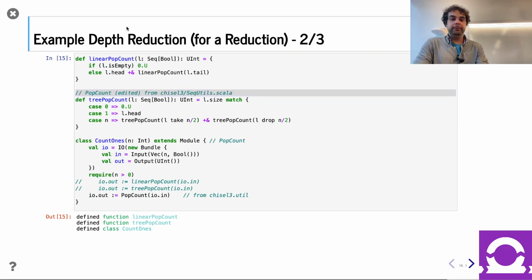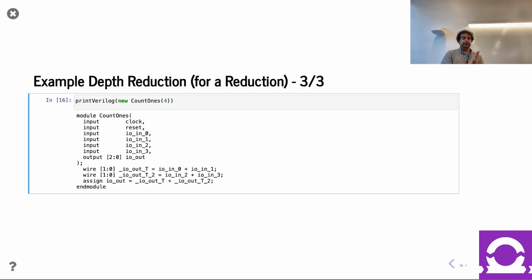So that's today's lecture on delay. Hopefully you got a flavor for this. Remember, delay in the real design comes from gates and wires. The tools do a lot, both to analyze and fix this. However, at times they get hung up, and that's where we can come in and help. The most common thing we're going to end up doing is inserting registers, helping with pipelining. And that's an architectural change. It needs to be done by humans for now. Hopefully, we'll have tools to automate that someday in the future. And then other times, like I just demonstrated, there's a logic depth issue. Very commonly this happens in priority encoders or things like that. And you've got to kind of deal with it.